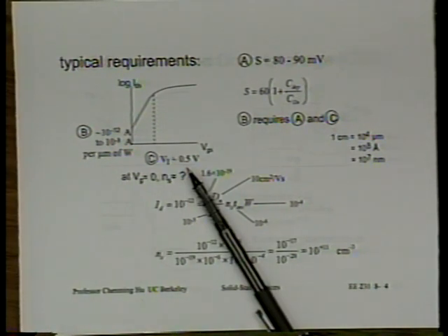Then you look at the critical path, because there are only a finite number of paths that really limit the speed of the circuit, right? Critical path. And there you figure out, hey, if I selectively reduce the VT of these 200 transistors, then the circuit speed can be boosted, right? So I will use the low VT transistor for those. You see what I mean?